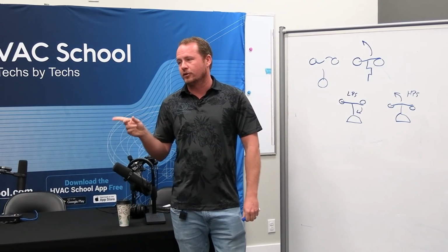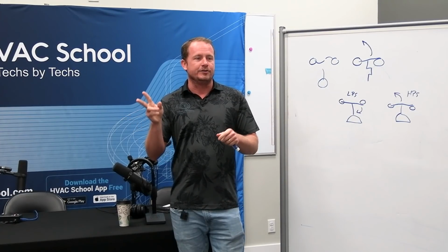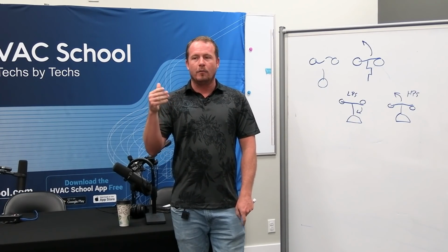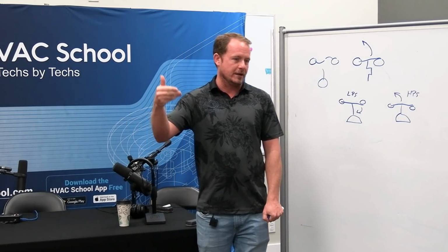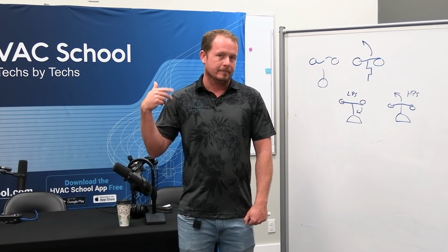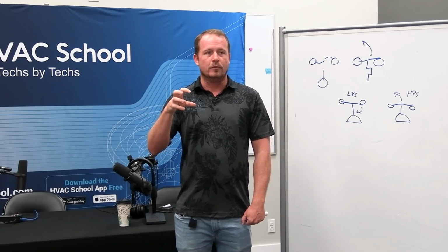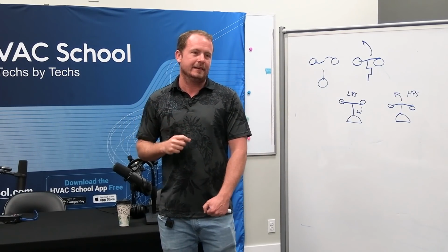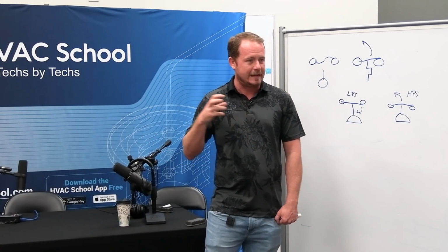Another thing that I wanted to mention quickly, because Sam said that you need to pinch off compressor stubs and braze them, how should you remove compressors and line dryers? What's the best way to do that? Cut them out. If you unsweat, you are likely to get a little fireball coming back at you. So it's a safety issue.